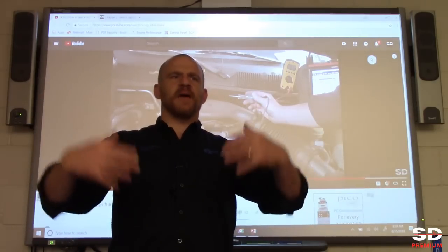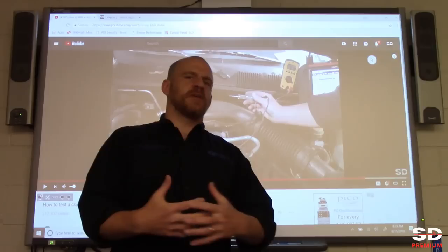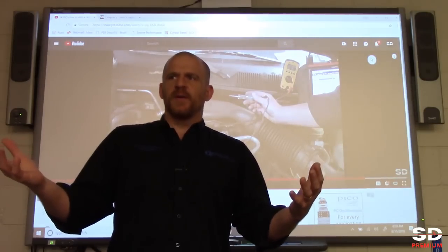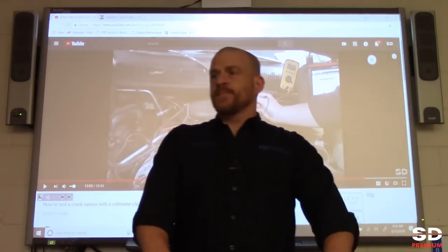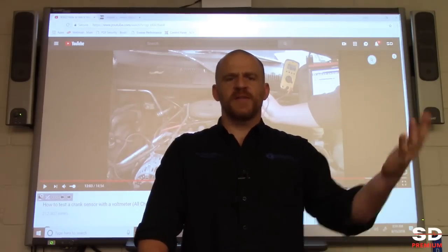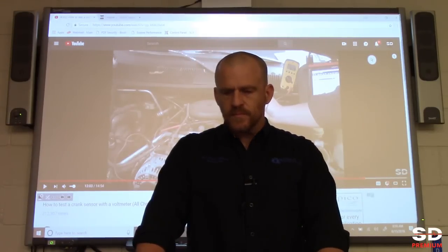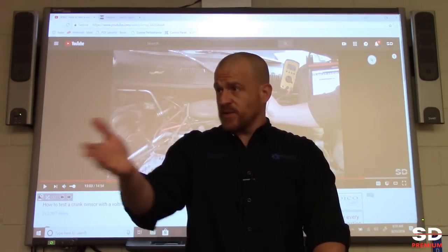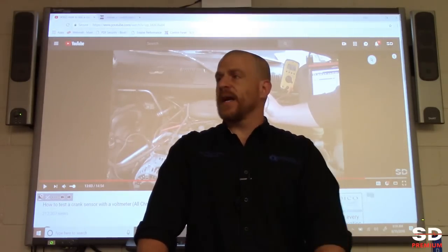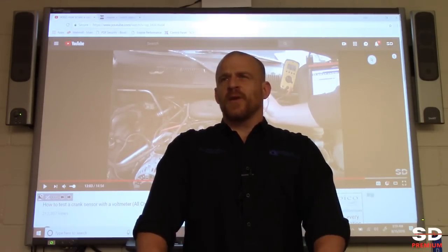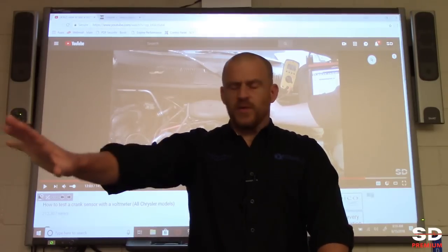Let's take a step back for a second. If I'm doing a switch input bypass test, which is what I'm doing, it's a Hall effect in this case, what am I looking for? I'm doing a bypass test. How do you know if the test worked? What am I looking for? You're looking for it to do whatever the sensor's supposed to. Correct. Depends on the circuit. So if you're messing with the throttle body, you want it to rev up. Yes, exactly. I can't think of a scenario where the throttle body, but you're absolutely correct.